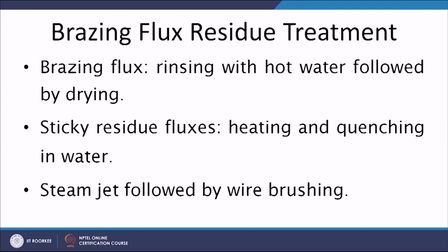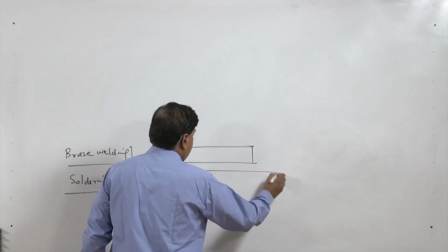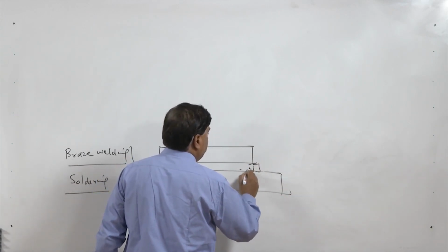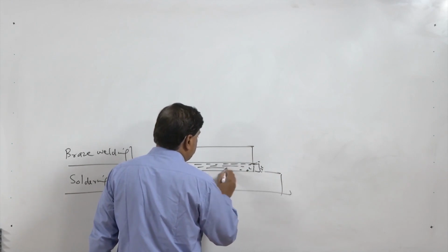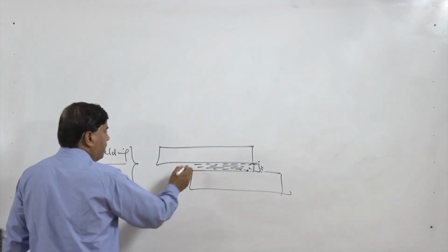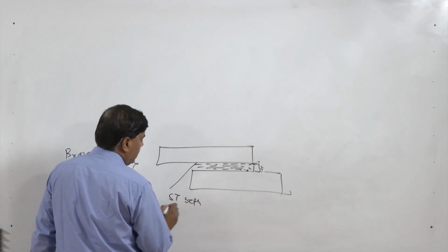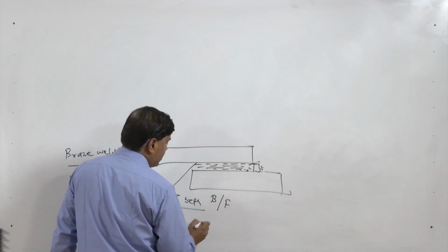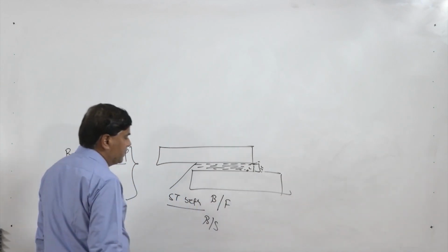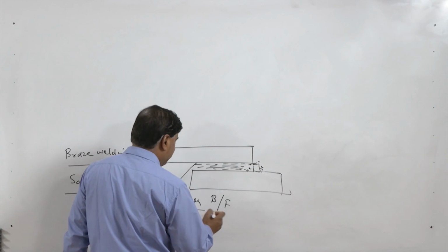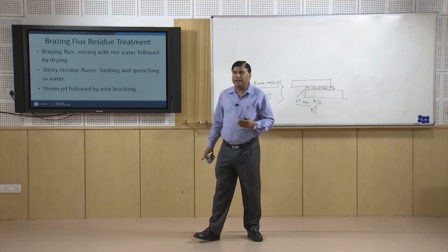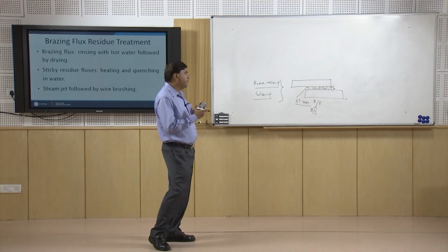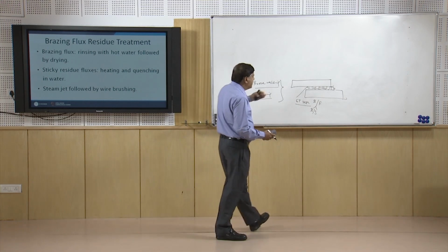Then once the solder is placed, how does it work? Say this is the solder, flux is also applied. So basically all will be reaching the molten state. Here the flux will also melt, solder will also melt. So depending upon the surface tension between the base metal and flux, and base metal and solder. The surface tension between the base metal and the flux being lesser than that between the base metal and the solder, the flux is pushed out in the course of soldering, and the liquid solder will be pushing it outside while interacting with the molten metal.